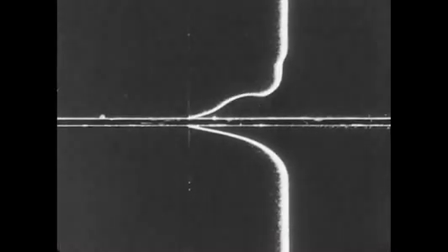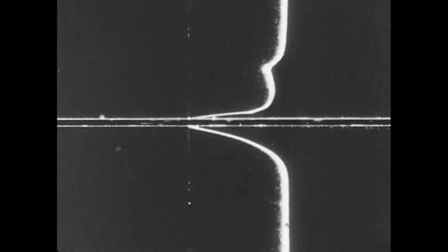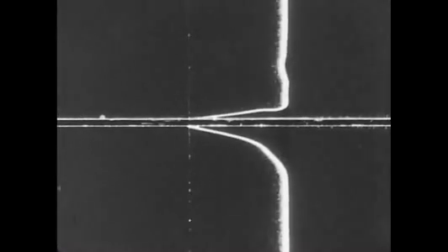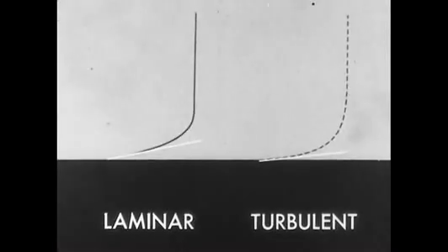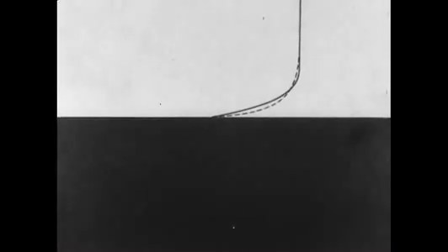The distribution of momentum in the two layers is also different. In the turbulent layer, high momentum fluid is moved toward the plate, and low momentum fluid is moved away from the plate by unsteady, random motions. There are larger shear stresses and more momentum in the turbulent boundary layer than in the laminar layer, and the turbulent boundary layer is slightly thicker. In the diffuser, the turbulent boundary layer along the bottom wall does not separate, while the laminar one does, because the three-dimensional interchange between regions of high and low momentum fluid in the turbulent layer is more effective than the molecular diffusion in the laminar layer.